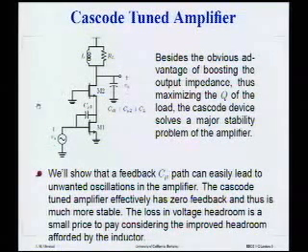But what's a lot more subtle, and something that we'll discuss when we talk about oscillators and stability in amplifiers, is that the real benefit of using a cascode is it eliminates the parasitic feedback from the output back to the input. It turns out that when you use an inductor here, it's very easy to build an oscillator if you don't use a cascode, if you're not careful. And again, this is something we'll discuss in more detail in a couple lectures. But the reason a cascode is nice is it really essentially eliminates that feedback path, right?